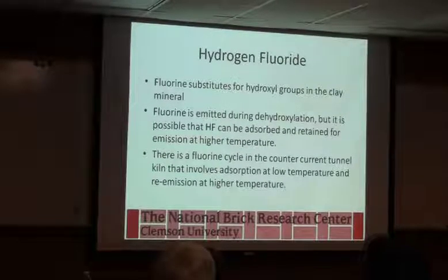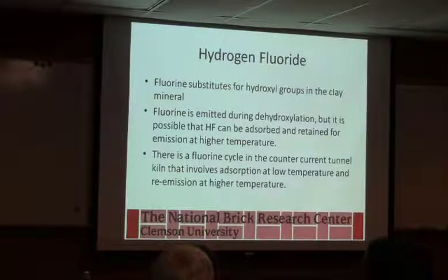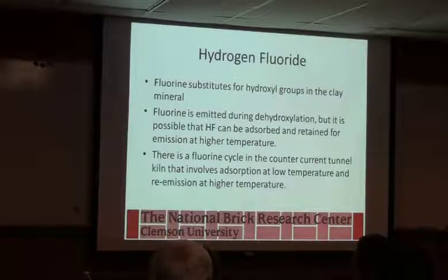Now, if you're dealing with liquid HF, which you're not, you're dealing with low levels in the air. Liquid HF can damage your bones if you get it on your skin, and we actually use it in the lab for this very reason. If we have a piece melt, you can put it in hydrofluoric acid and it'll eat the glass off of it, and it'll leave the alumina parts for the thermal analysis equipment behind, and it cleans it up real nice.